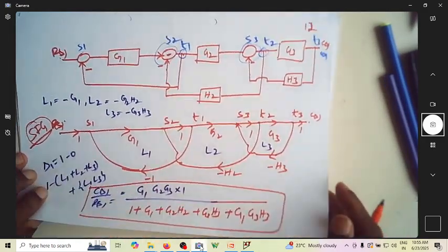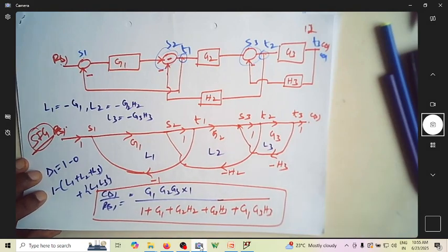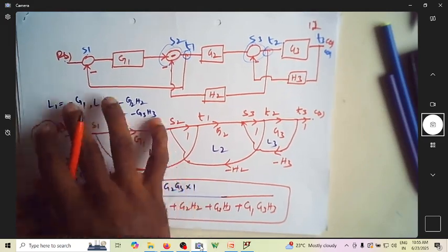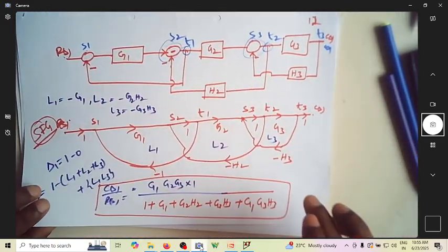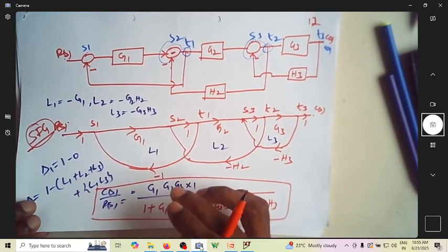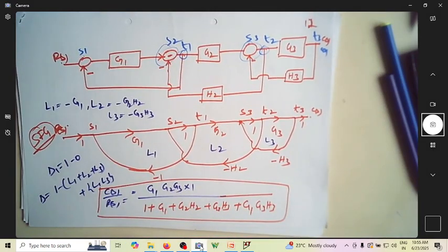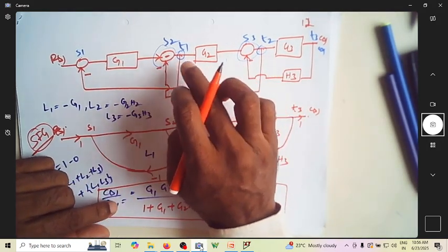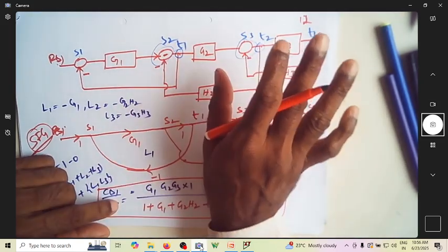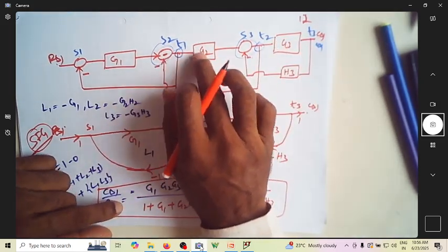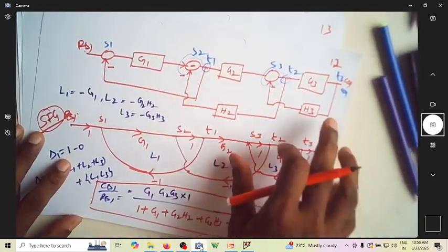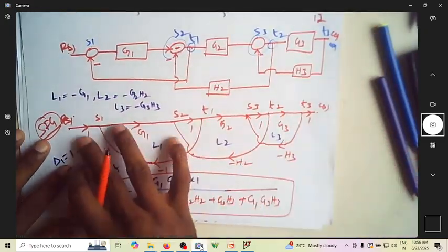Maybe in the previous problem you might have seen that using block diagram is easier compared to SFG. But of course, it depends on the problem you are looking into. So look at the problem and decide which method you want to use. If there are loops without any takeoff and summing points, you can simply reduce. If there are some hurdles, don't go for the block diagram reduction technique. This will be the easiest one.